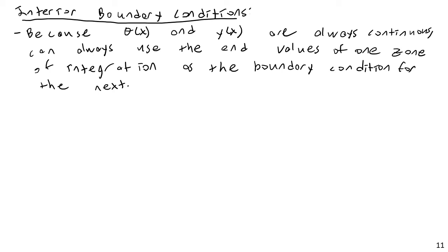Any other questions? So a pin connection would be the same as a pin support? Yes, a pin connection would be the same, but it has zero moment on a pin connection. Exactly. So it has zero deflection, but it has a different slope though? Are you talking like an internal pin? Okay, an internal pin will not necessarily have zero deflection, because it's not actually supported at that point, but it would release the moment at that point. Okay?